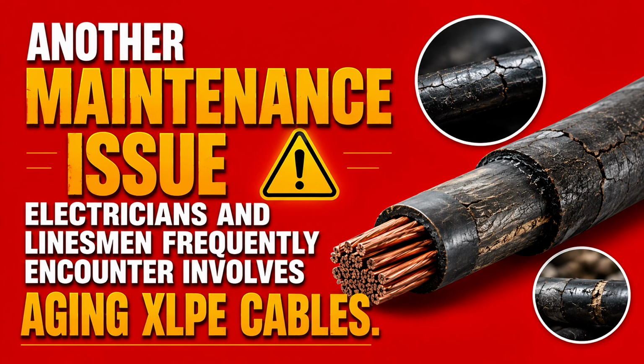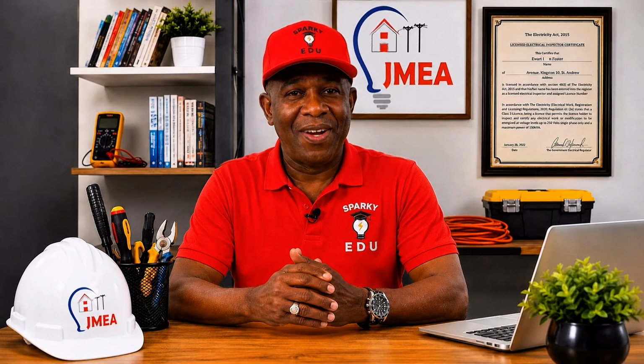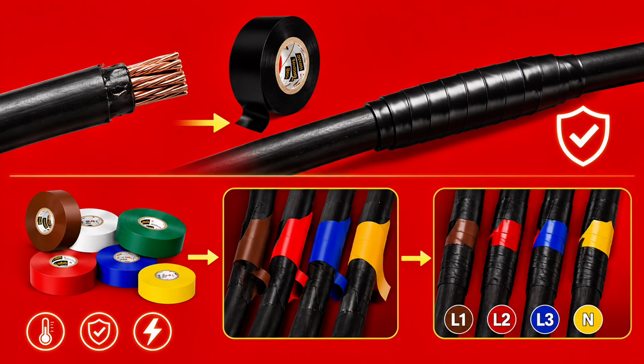Another maintenance issue electricians and linesmen frequently encounter involves aging XLPE cables. After years of exposure to heat, sunlight, and moisture, insulation near potheads can deteriorate, exposing conductors and increasing the risk of faults. Preventative maintenance often includes re-insulating exposed conductors using approved high-temperature electrical tape.